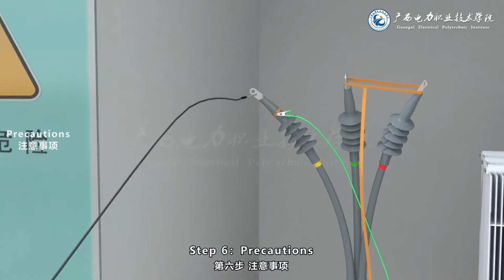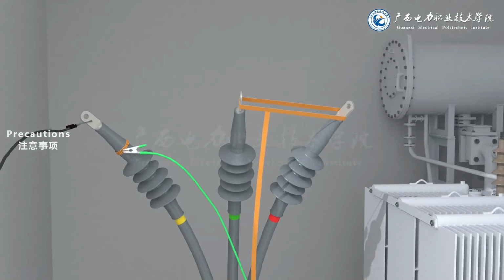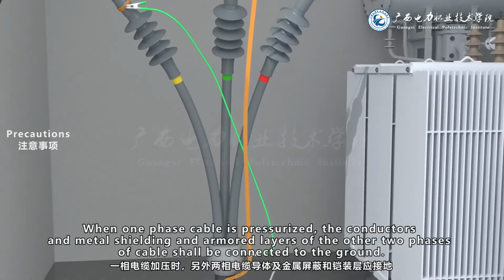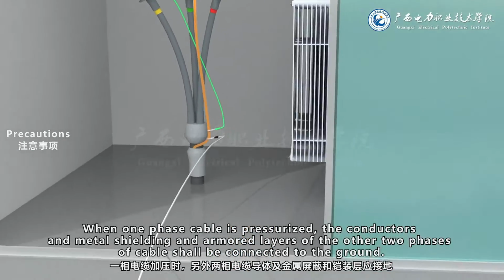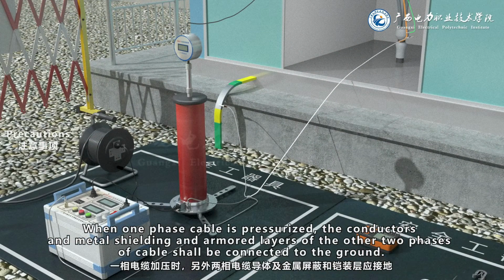Step 6. Precautions. The cable test should be carried out phase by phase. When one phase cable is pressurized, the conductors and metal shielding and armored layers of the other two phases of cable shall be connected to the ground.